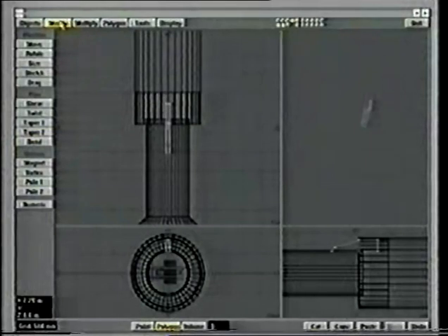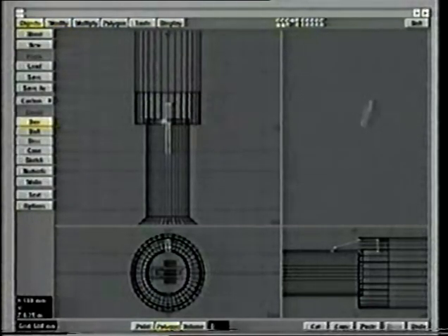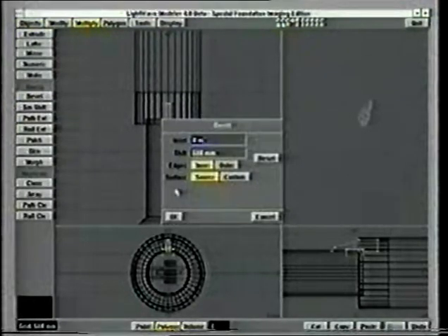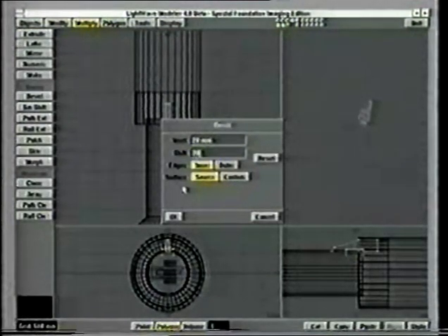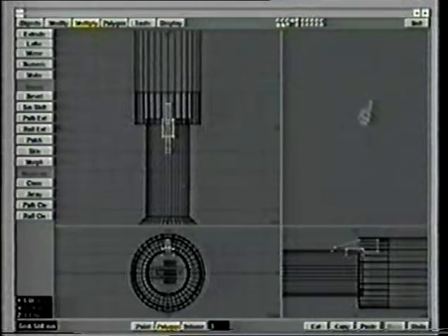Now let's put some more boxes in there to make it look as if it's connected to the cylindrical surface around here. So let's go objects box once more. And let's bring that up out of the surface of the fuselage there. Let's make it. And then just take the polygon on the top and do a little bevel on that of say 20 millimeters. Lovely. So there we go.